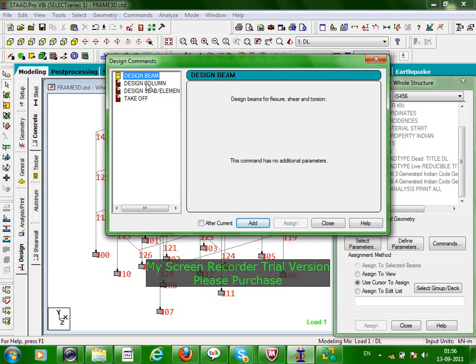Because this is ineffective here. In Indian design consideration we provide continuous top and bottom bars, with alternate bars bent up, and we do not provide unnecessary steel, because our approach is slightly economical. Abroad, they provide either continuous top or continuous bottom steel in a slab, just like a beam.